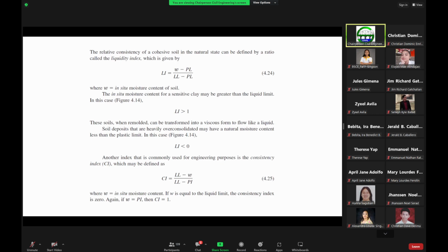I just recall that lately we were doing drilling work somewhere in Luzon. The borehole was about 10 to 15 meters away from an inactive fault line. We were investigating the borehole near an inactive fault line. While we were measuring the groundwater levels every day, we found out that the groundwater level was decreasing. It's not stable. So maybe the water is going somewhere else, due to the location of that inactive fault line.